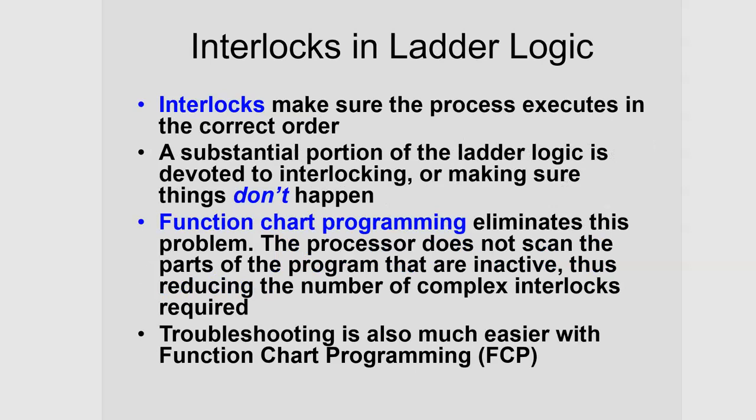And then there's this idea of an interlock. So let me say a little bit about an interlock. There's physical interlocks and then there's software interlocks. An interlock can be as simple as an off-on switch, a main switch in the factory that I can put a padlock on so that I can keep someone from turning it on. Basically, an interlock is a way of preventing something from happening.